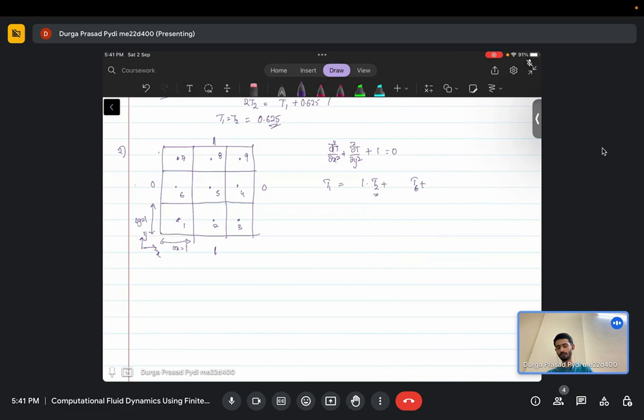So here you have a 1, here you have a 1, and since the source term doesn't have any contribution from the gradient, your AP will be summation of these two values. So you have 1 plus 1, so a summation of 2, but then you have the half cells here. So you are getting a 2 from T1 and T6, and then you have a half coming from the other two borders. Plus you have a source term. Source term is essentially 1 here.